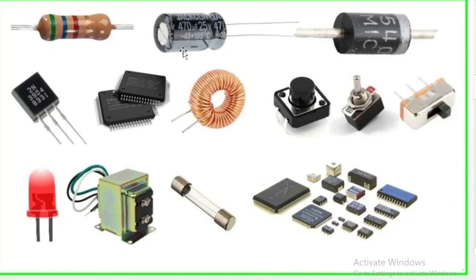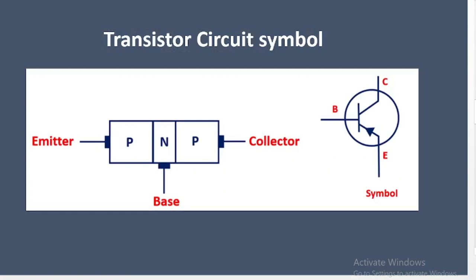You would have to construct them yourself. And the basic building block for a basic current source is actually a transistor. Any class of the transistors, either the BJT or MOSFET, can do quite a good job.